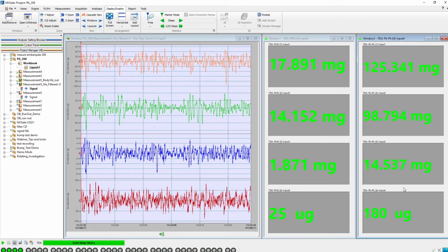It's the same for the seat. We have a really low level of vibration as we don't have any rotational vibration on the seat of the driver. So you can see that thanks to this indicator, this filter, it becomes really easy to compare the rotational vibration between different measurements. It could be different cars, or it could be different steady states.